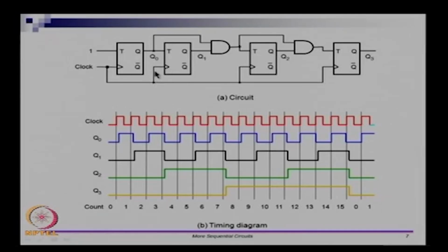So, the triggering signal is clock, the sampled signal is Q0, and Q0 remains at 1 when the triggering signal clock is coming in. As long as the triggering signal comes in only when the sampled signal is stable, then the setup time would get satisfied. So, it has been stable for almost one clock period, and for a good flip flop this should be enough. So, this toggles.